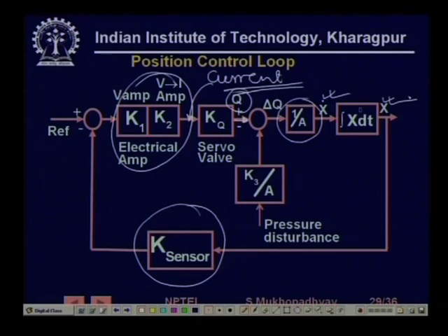This is like a block diagram. Similarly, the flow that you are assuming is going through because of your nominal value of KQ can sometimes be slightly changed if the supply pressure of the pump changes. To model that, they have put a pressure disturbance block.